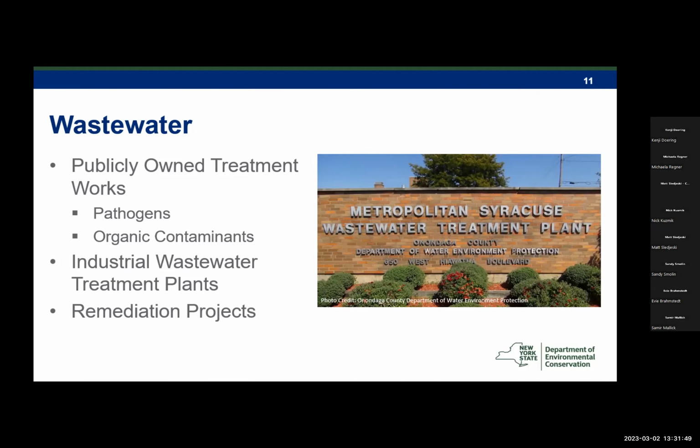And this technology could also be applied in the field at remediation sites. For instance, some sites require contaminated groundwater to be extracted, and in some cases, this water must be transported to an off-site facility for treatment. If an electron beam were brought into the field, it could be used to treat organic contaminants on site, eliminating or reducing the cost of off-site treatment. Proper shielding of the beam would be required for safe operation, which I will touch on more in a few slides.